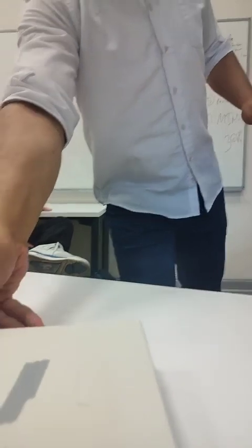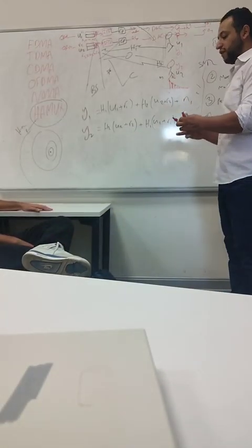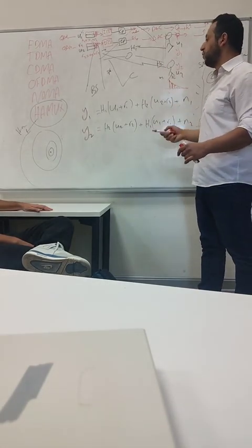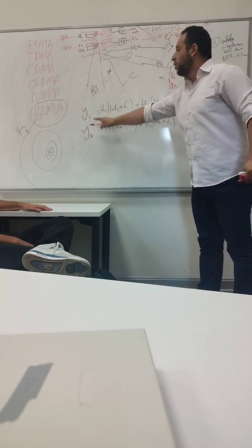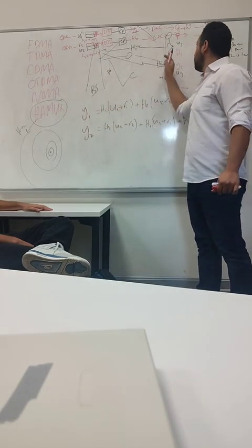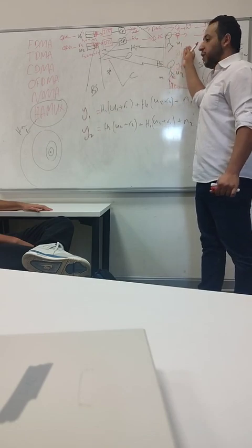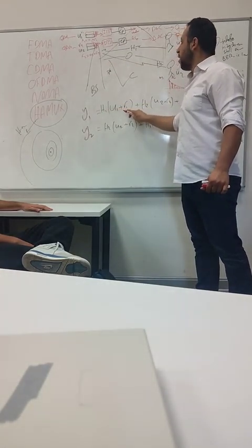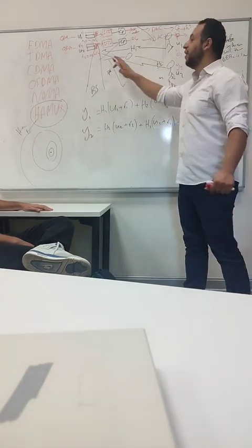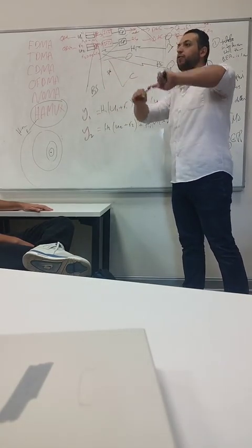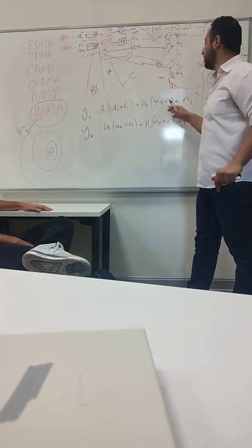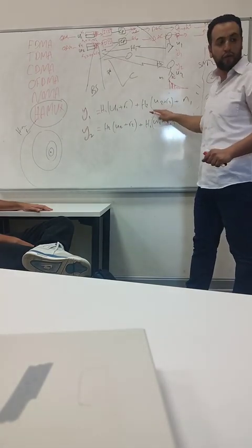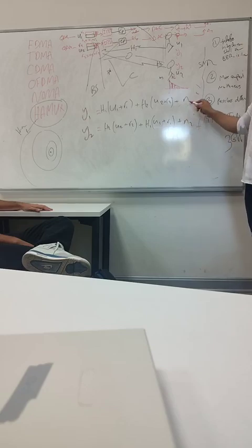And we said if we ask you to do mathematical modeling for this, what happens here, you have to write the user 1 and user 2 data. What will be the signal that's captured by user 1? Here, H1, the channel between them, times U1 plus R1, and because the antenna at the transmitter propagates in all directions, it can also capture the signal related to user 2, which is U2 plus R2, multiplied by its channel, plus noise.